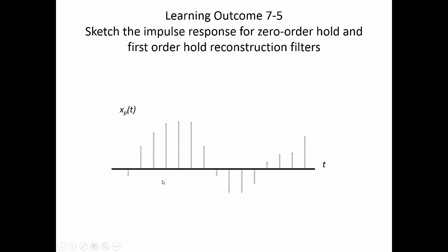Let's consider each of these impulses. Around this particular impulse, when we do our convolution, linearity is then going to give us this as an amplitude for our triangle. When we take just this one, because we can add them separately by linearity, the area, the scaling factor for this impulse, is then going to form a scaling value on this triangle. Likewise, for each of the next one, the scaling value on each impulse, which is the amplitude for xp of t at that time point, will then scale our triangles.